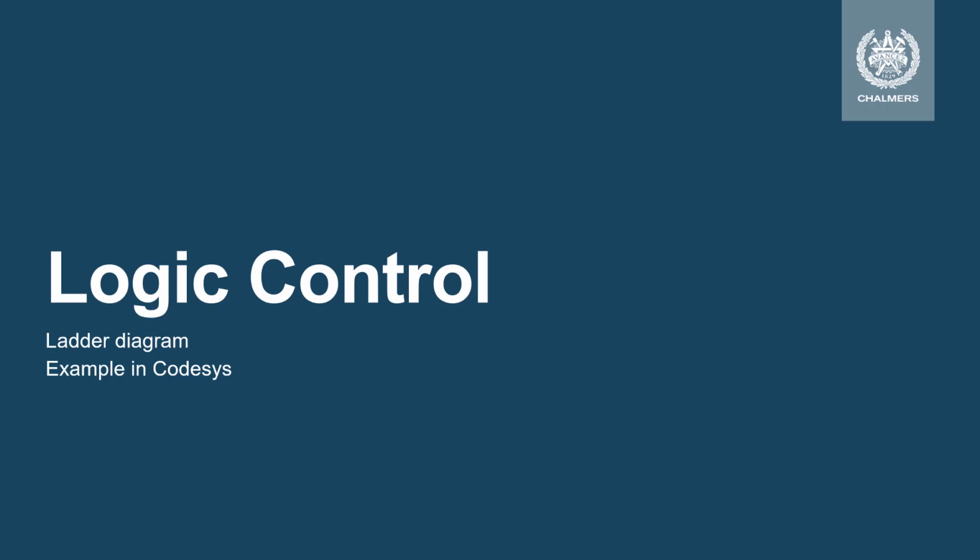Now it's time to jump into the first programming language in PLC systems, ladder diagram. In the previous film, I showed an example in relay logic, and that is because ladder programming comes from relay logic. I will use the same example as for the relay logic to see the similarities, and I will also show how to program this example in Codesys.